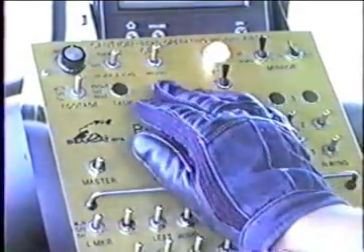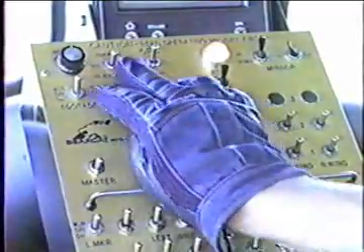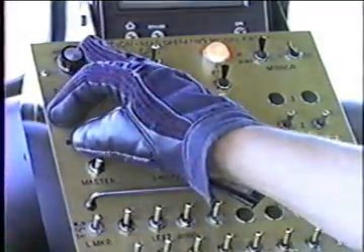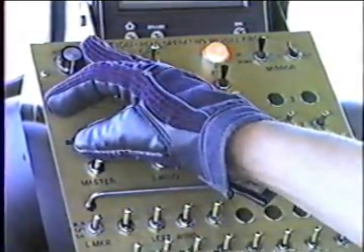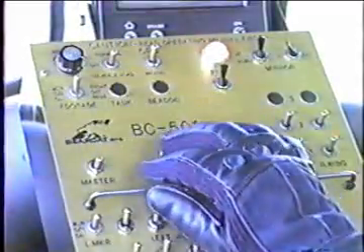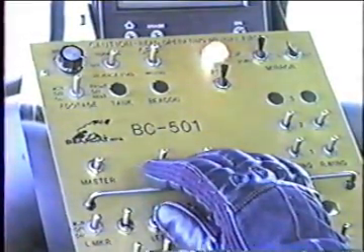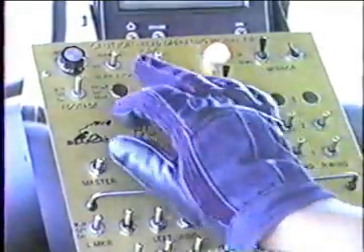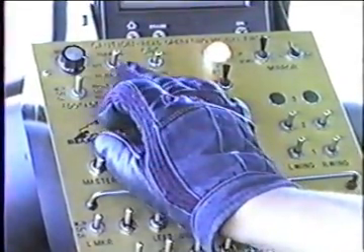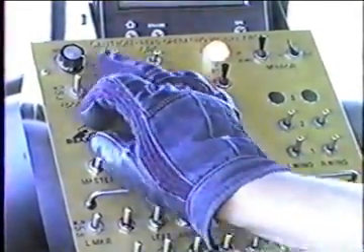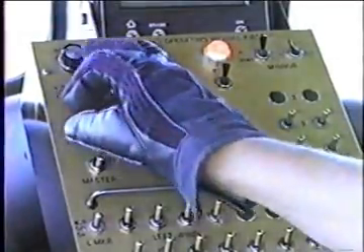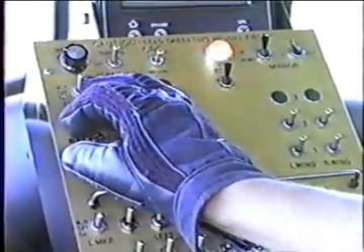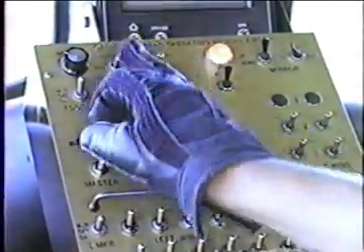No CRC manual switch, it's always in manual. Forward, and we would control speed of the pump here. On the computerized truck, if for some reason we need to do something in the manual position, we put this into manual, and with the truck running, we can control the speed of the pump with this knob. Of course, in the forward direction for any spreading, reverse direction for loading.